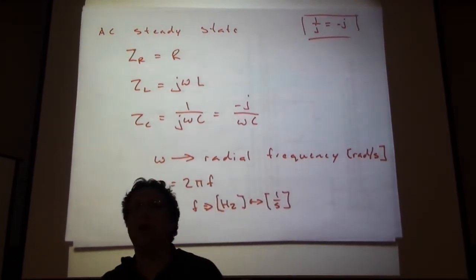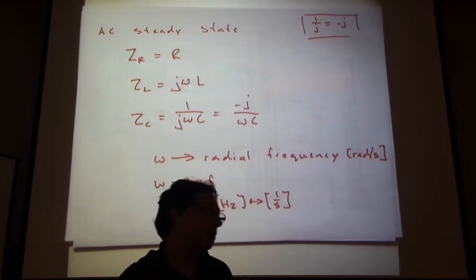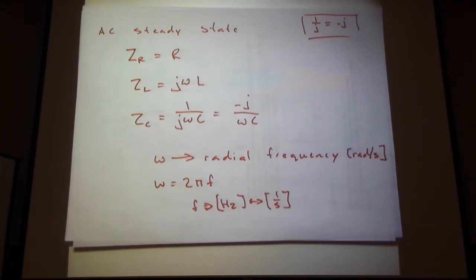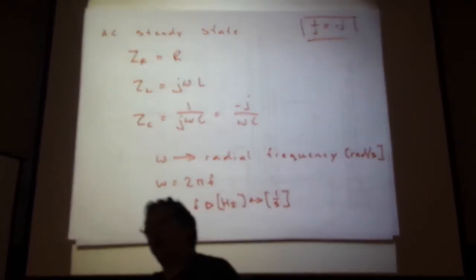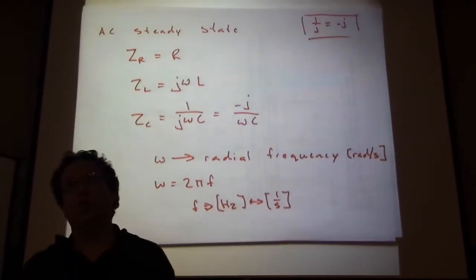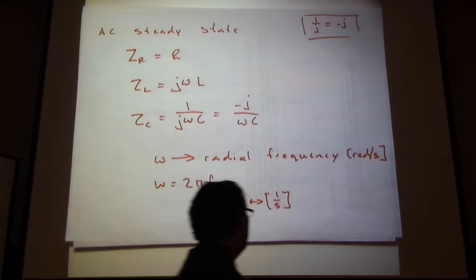The frequency going to 0, that's a constant. Well, as omega goes to 0, what is ZL? By observation, we substitute in omega equals 0. What's ZL? And how does that correspond to the DC steady state from Unit 2? We know the DC steady state of an inductor is a short circuit. So here it is, kind of verified mathematically.